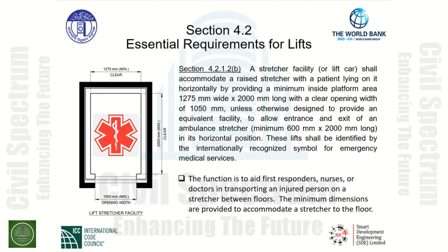Dimensions are indicated of 1,275 millimeters wide by 2,000 millimeters long, with a clear opening width of 1,050 millimeters, unless otherwise designed to provide an equivalent facility to allow entrance and exit of an ambulance stretcher.